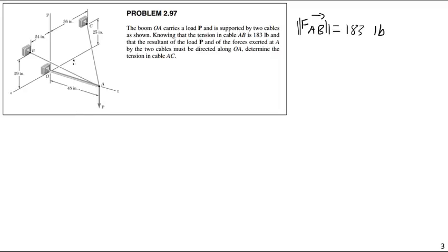Now let's see, what else do I know? I know that the Z component of this force must balance the Z component of this force. FABX must be equal to FACX. Well, equal and opposite anyway.